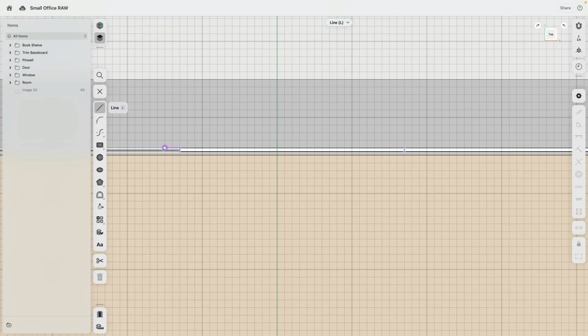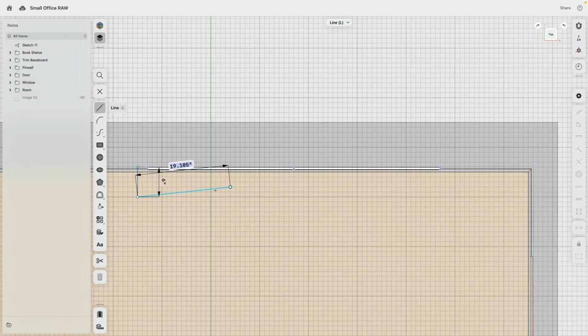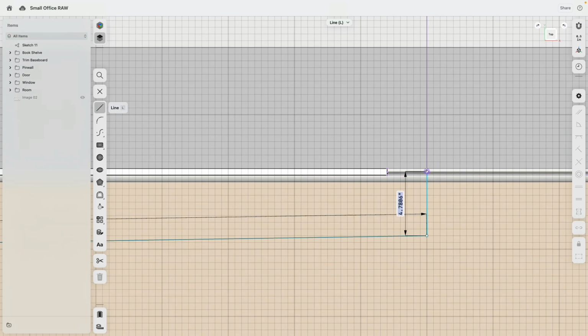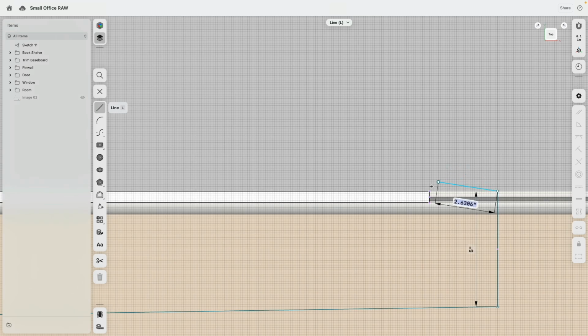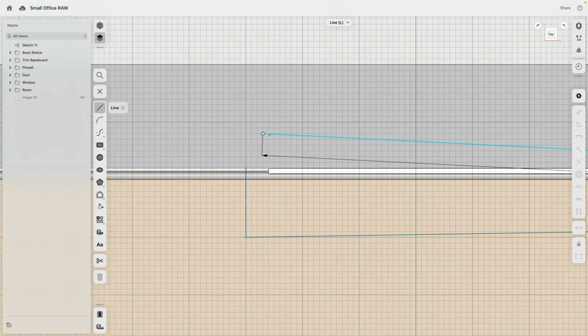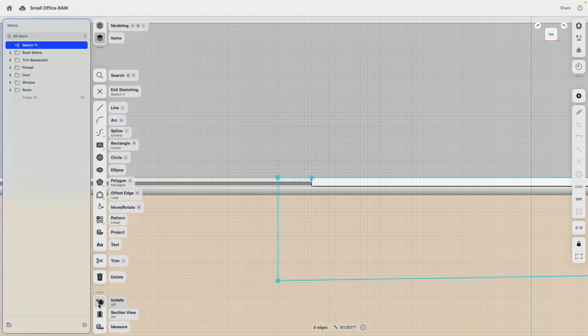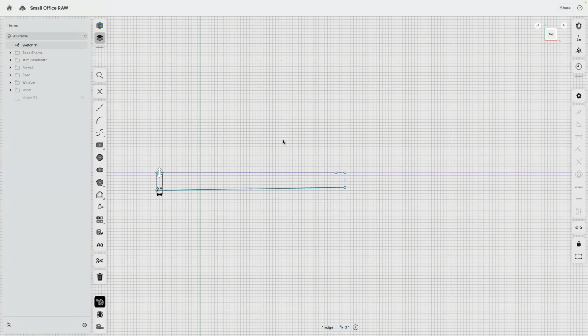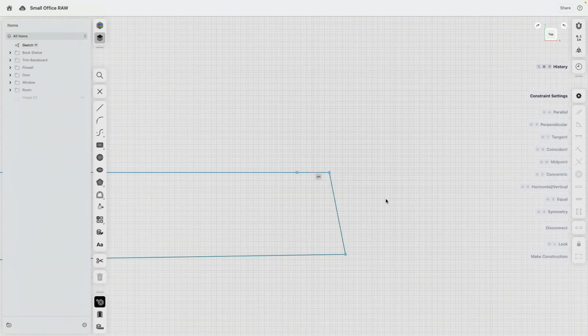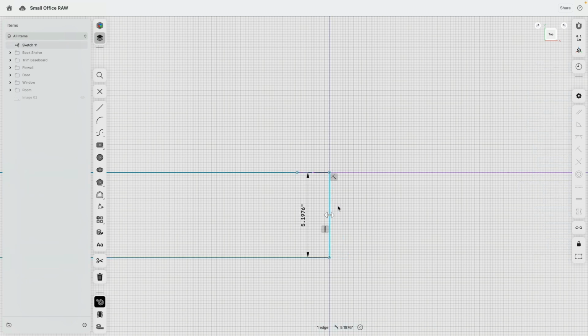I need to figure things out a little bit. So there, let's say 6 inches, and then back to there, and connect it to there and there and there. And then this sketch now I'm going to isolate because I have the correct position. These two lines will be equal. I select everything and make it horizontal vertically. That's going to be, let's say, 5.5.